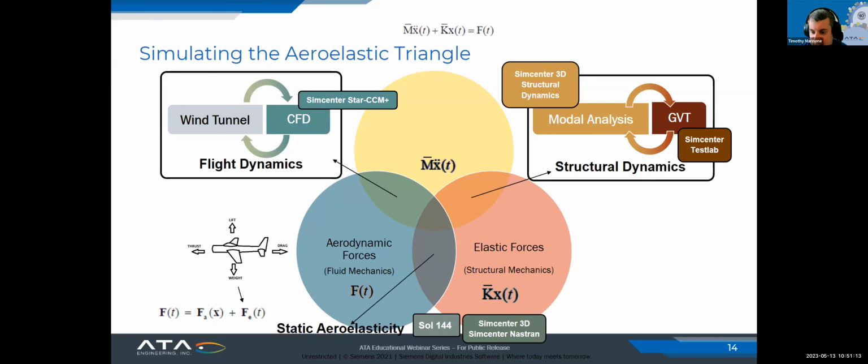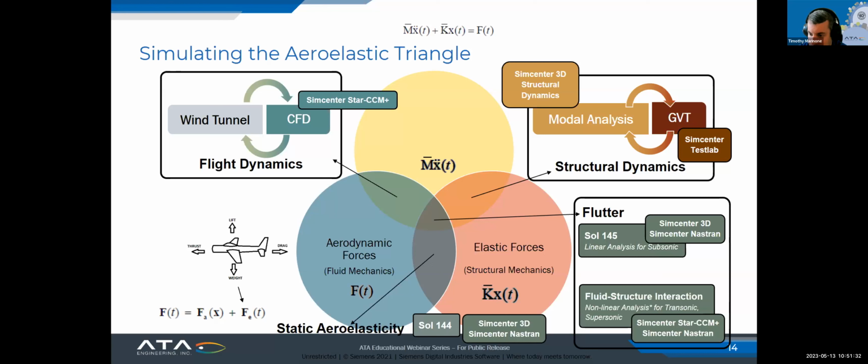Sorry, interaction between our elastic and aerodynamic forces. And so in this case, we're going to do a static aeroelastic analysis using SimCenter 3D and SimCenter Nastran using solution 144. So once we've gotten all those different pieces together, we can finally do our flutter analysis.